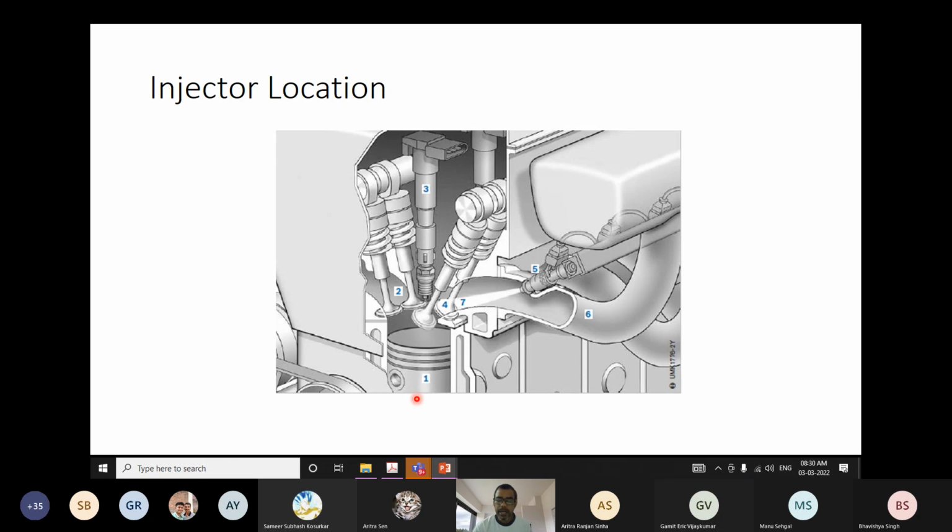If it is a misfire, then what will happen? Whatever hydrocarbons are in the combustion chamber will go to the atmosphere without burning. So it means you are going to have larger HC emissions, hydrocarbon emissions. Then what happens? During the starting time, you have to control your system in such a way that the combustion must start within a very minimal rotation of the crankshaft.